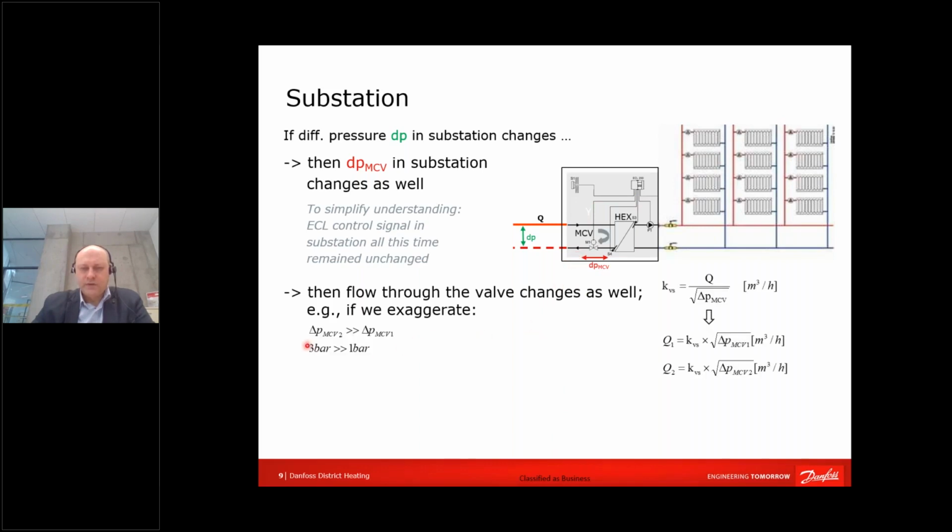And let's presume that delta P on the motorized control valve is much larger than before. From 1 bar, it jumped to 3 bars, for example. We can presume that flow suddenly increased almost twice. And naturally, the building is not capable of taking all that energy. So here we have a high return temperature, which might be compensated by its sensor.